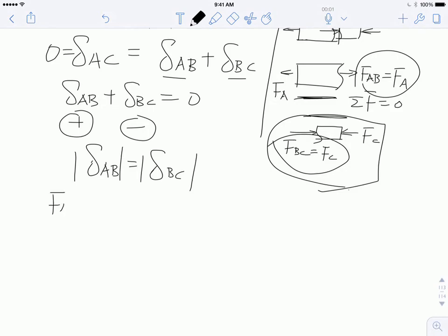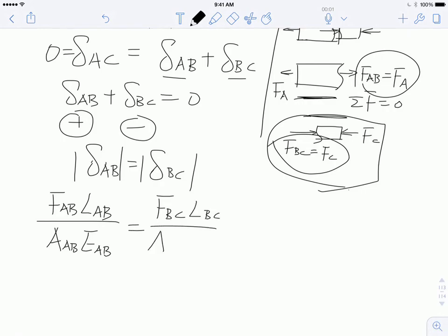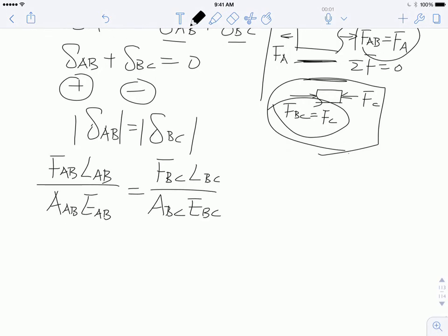Delta AB is nothing but FAB times LAB divided by AAB times EAB. That's just the standard definition we learned 2 weeks ago. The other one is nothing but FBC times LBC divided by ABC times EBC.